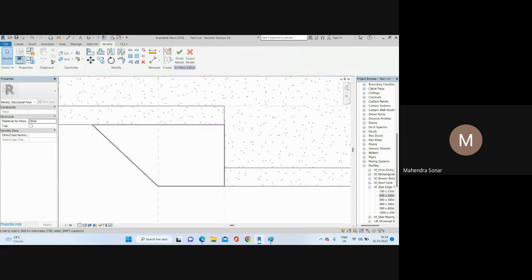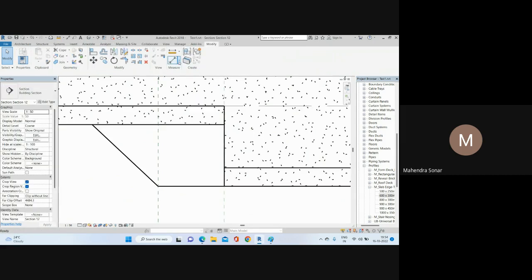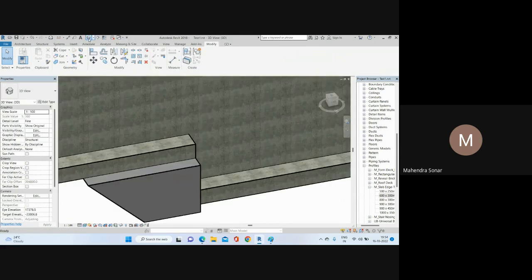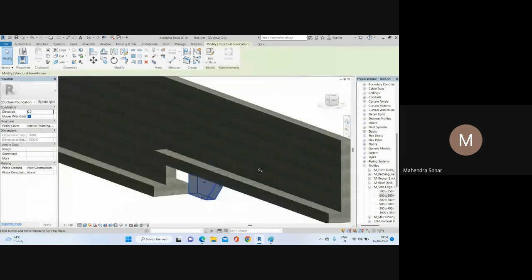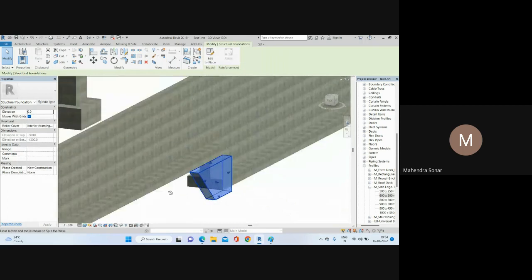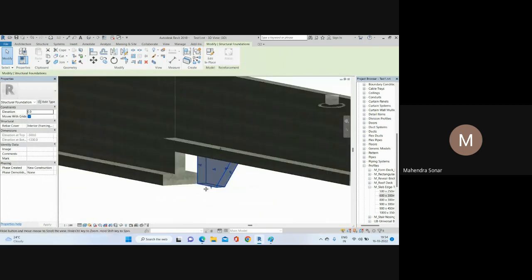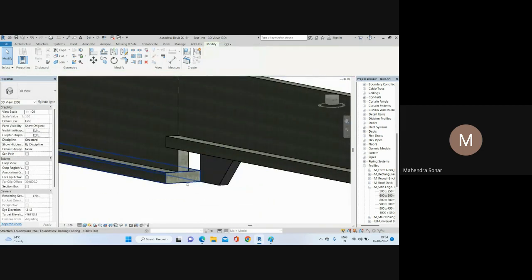and if you go to your 3D model, once you complete, just click here finish. Okay, and if you go to your 3D model, this shape has been added here, right, like that. And after that what you need to do is give the command. Okay, just type AL for align and select this face, and you need to select this face. I want to align with this.